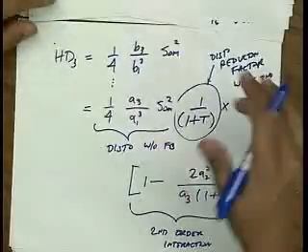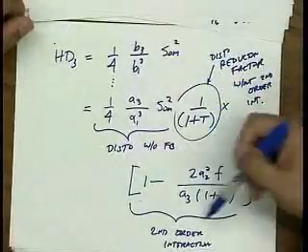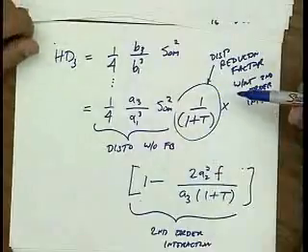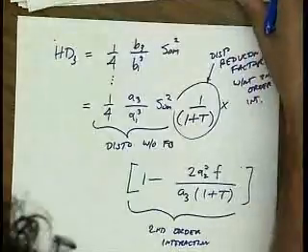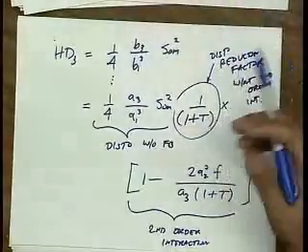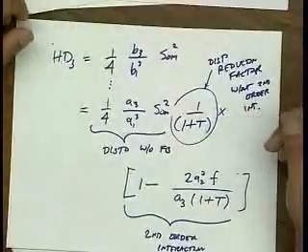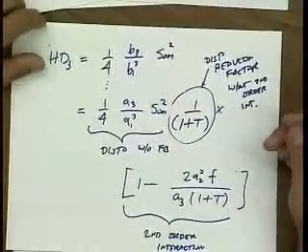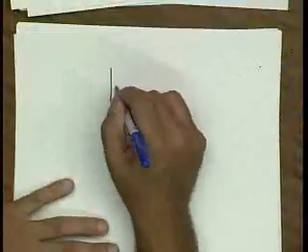So what's happening is that the action of the feedback certainly reduces the third harmonic, but it also generates an additional third harmonic. Just to give you a little bit of intuition on why feedback reduces distortion in the first place: think of it in terms of an op-amp.